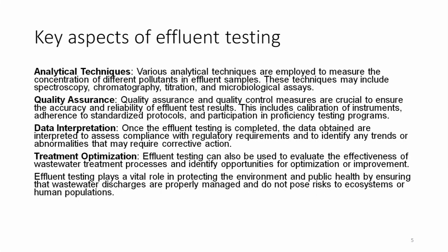Quality assurance and quality control measures are crucial to ensure the accuracy and reliability of effluent test results. This includes calibration of instruments and adherence to standardized protocol and participation in proficiency testing programs, because it is very important whether my test method is correct or not and whether it has a repeatability or not, because just by doing test one time does not ensure that it is the correct result.